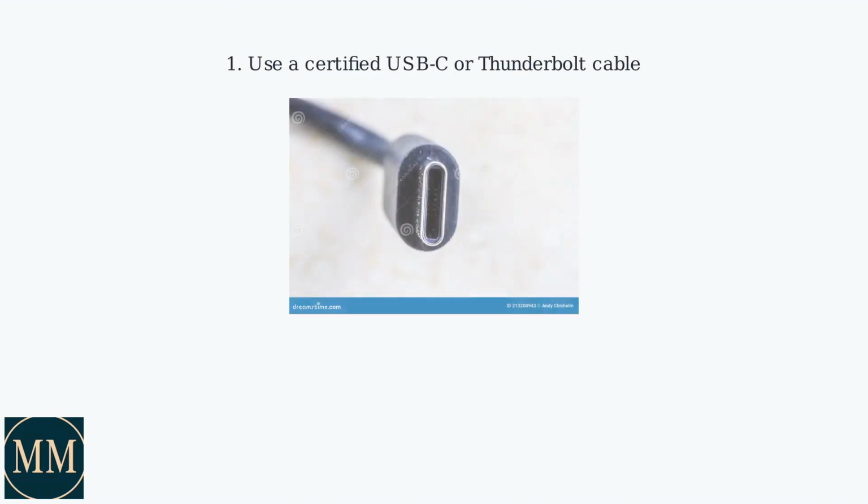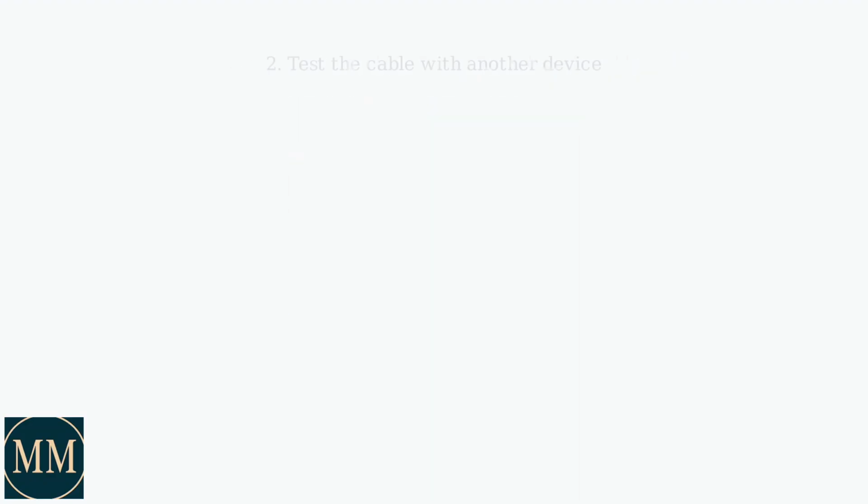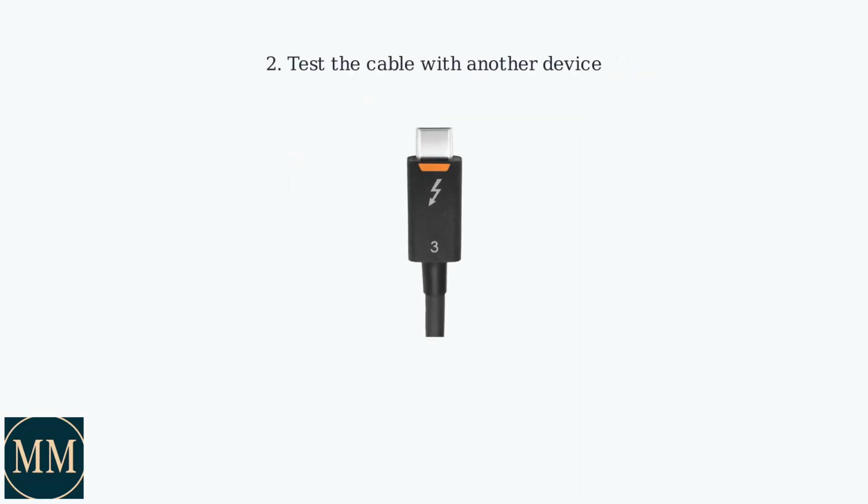Experiencing issues connecting your ASUS monitor to your MacBook Air Pro via USB-C or Thunderbolt? Let's troubleshoot. First, ensure you're using a certified USB-C or Thunderbolt cable. Faulty cables are a common culprit, accounting for 30% of reported failures. Test the cable with another device if possible.